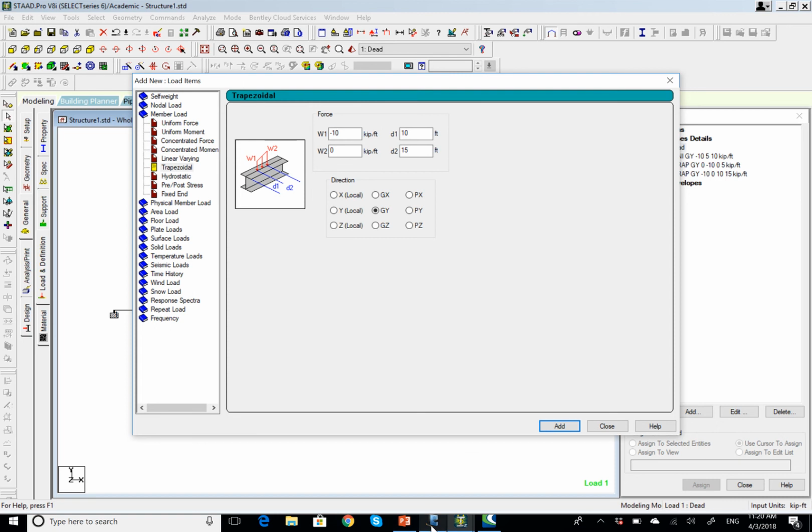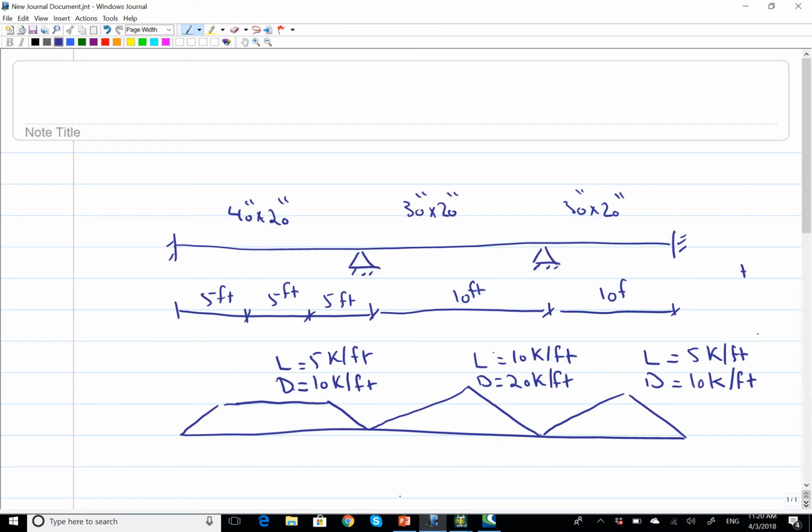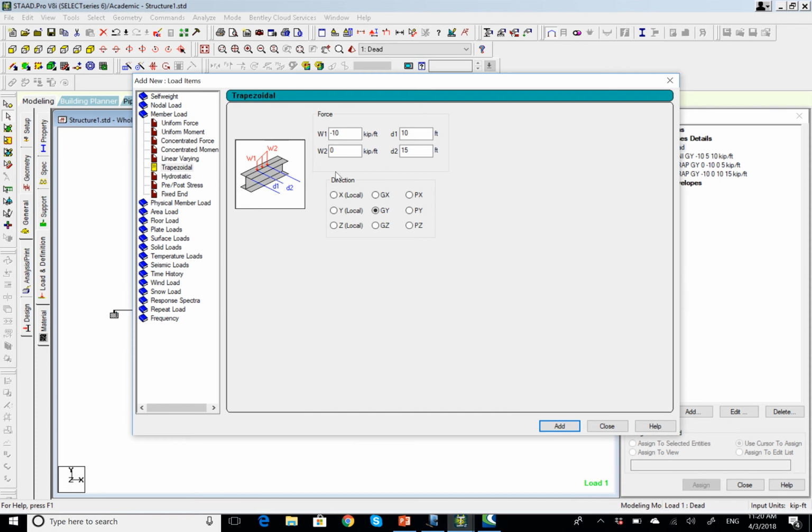And then let's go and add the loads for this member, okay? The intensity is 20. It has an increasing load and then a decreasing load, okay? From 0 to 5, it's increasing, and then from 5 to 10, it's decreasing. So let's add this, and it's 20 kips. So here, this is trapezoidal as well. It's negative 20, okay? It starts with 0 and ends at negative 20, and this starts at 0 and ends at 5. Okay, everyone did this?